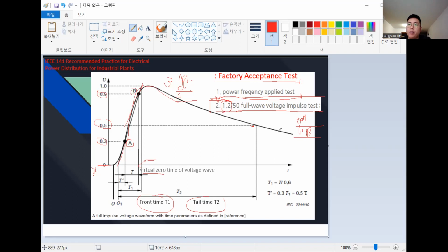Lastly, because of the LC circuit, vibration and transient response happen, and we cannot avoid it. That's why we need the insulation test, because it causes insulation damage. There are voltage variables that cause insulation damage, or insulation or dielectric breakdown, which mean the same thing: voltage magnitude, duration time, and slope.